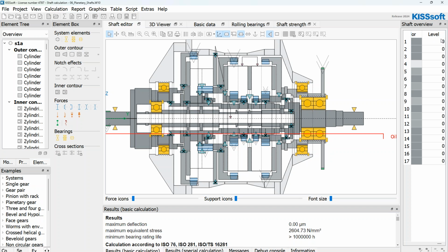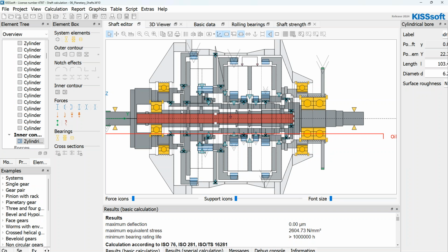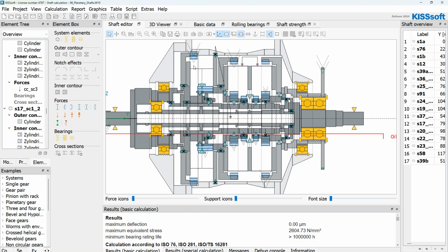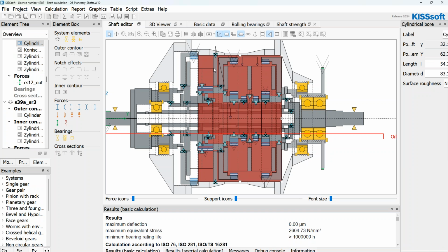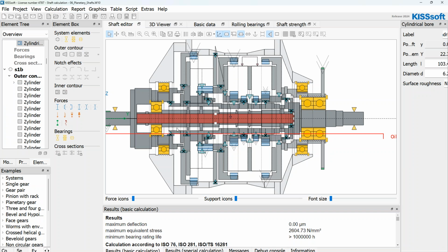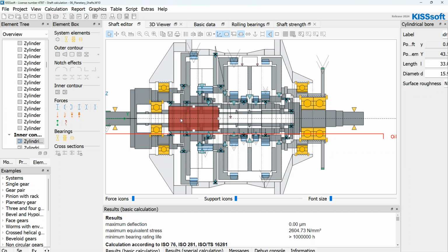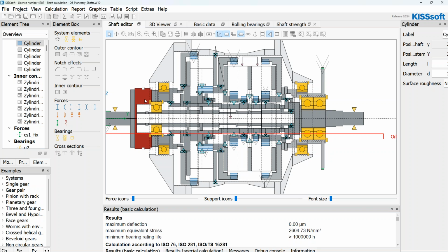In this example, I don't specify any levels, and still you see I can click into the bores, and the selection of the shaft is now defined so that the bore with the highest diameter will define which shaft is selected. This is now very comfortable and very convenient to handle, so that by one click, I get the corresponding shaft selected.